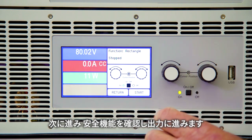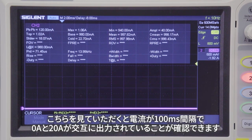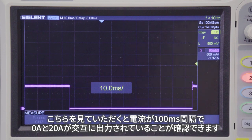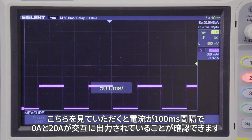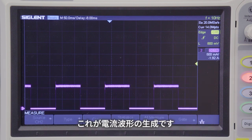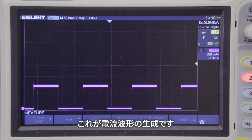Once this is loaded, let's get rid of these and start it. What you'll see here is, let me get this a little bit finer, we've created this pulse width modulation where there's 20 amps on for 100 milliseconds, 0 amps off. That would be, again, creating pulse width modulated current waveforms.